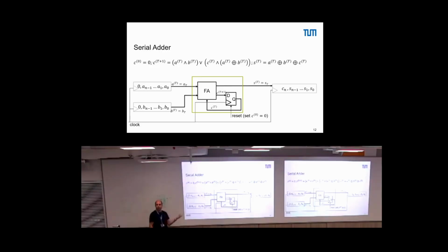Where do we use the adder usually? In an ALU, right? Now assume you have your smartphone, and your processor should do a simple operation. It should compute A plus B. What happens virtually all the time. So you want to run your system on, I don't know, a gigahertz clock. So your ripple carry adder is probably too slow.